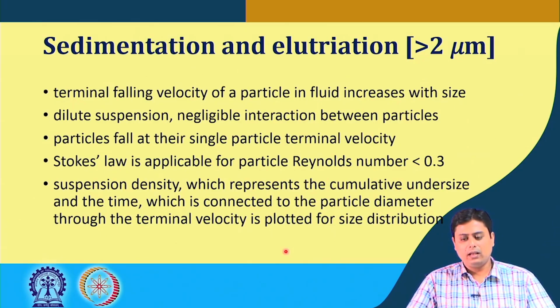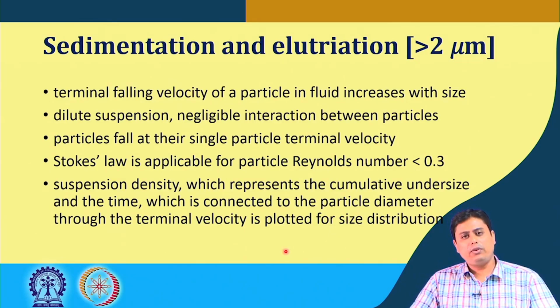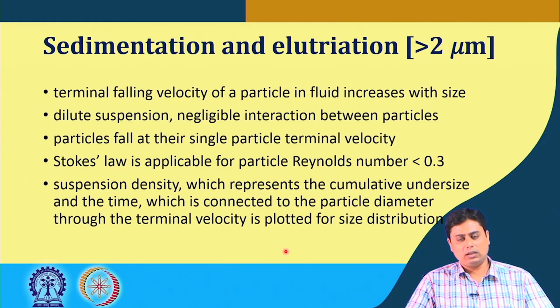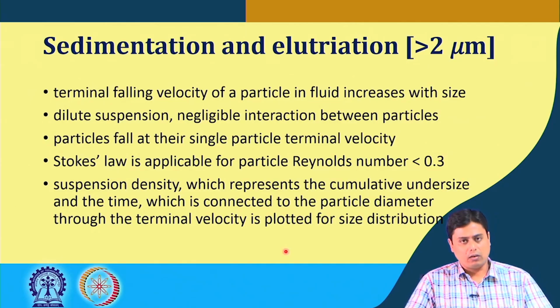By this technique, typically 2 micron particles can be separated, but if we apply Stokes law in water, the calculation shows that particle sizes of 50 microns and larger are easily determined by this when the fluid is water.